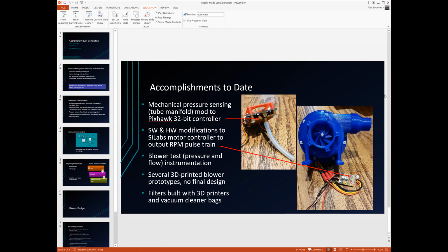Bearing failure. I mean, what are the moving parts in this? There's a piece of plastic that spins around and a ball bearing motor, which would have its lubricant replaced with a better lubricant, one that's more stable at higher temperatures. I think bearing failure could be a problem with these. Most of these are made with not the highest quality bearings. And redundancy is an option here also.